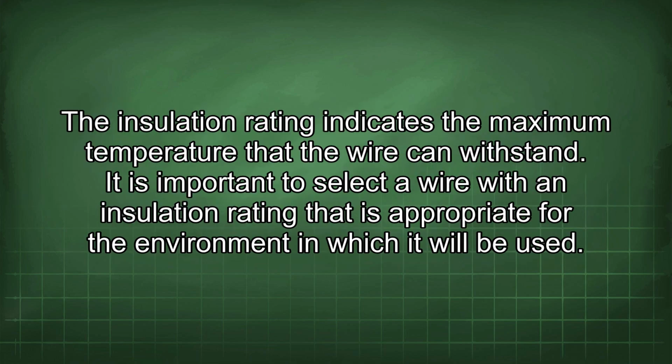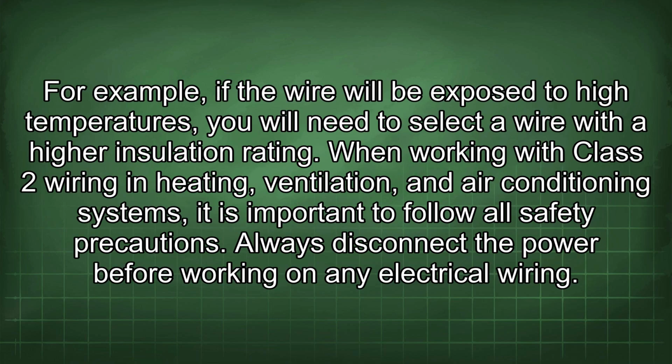In addition to wire size, it is also important to consider the insulation rating of the wire. The insulation rating indicates the maximum temperature that the wire can withstand. It is important to select a wire with an insulation rating that is appropriate for the environment in which it will be used. For example, if the wire will be exposed to high temperatures, you will need to select a wire with a higher insulation rating.